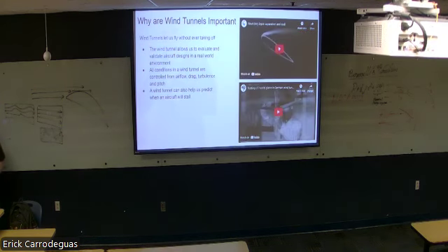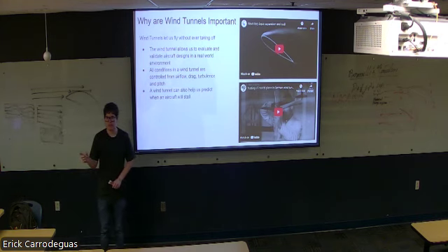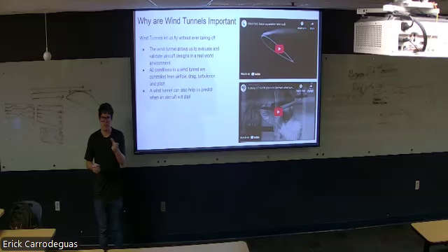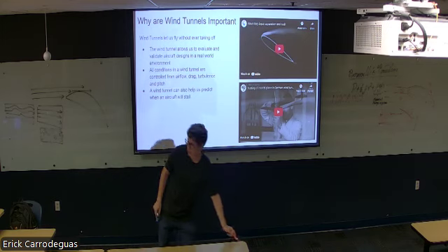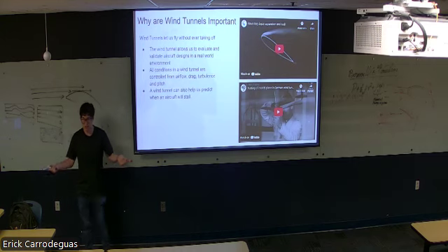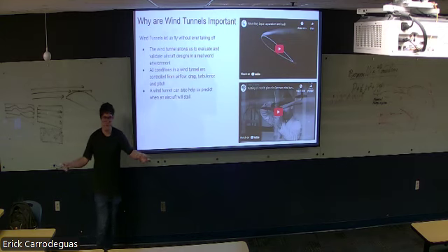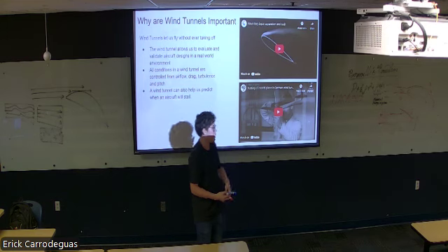So yeah, this is why wind tunnels are important. Basically, if we use the right wind tunnel and we scale the right Reynolds number, we can test our plane design. Let's say the ultralight would be the distance from this desk to here, as of now, that's the expected ultralight length. If we want to scale it, it'd be like a 10th scale, or even smaller, maybe a 20th scale, for it to fit in the wind tunnel.